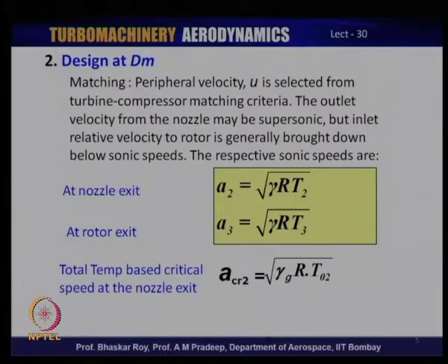Now, if compressor design is going on parallelly, or has already been undertaken, the speed of the compressor, the RPM, may be already selected or in the process of being selected, in which case the RPM of the particular turbine spool would also be selected.